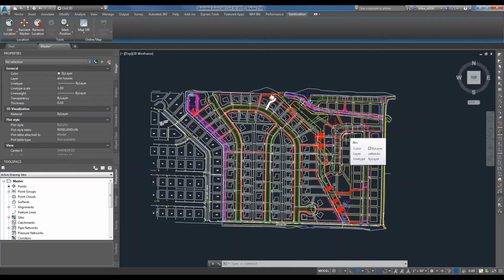However, in Civil 3D, we use COGO points, short for coordinate geometry points. They're a little bit different from those normal AutoCAD points. You could have plenty of properties associated with them. So you could have point numbers, point names, descriptions. So if you are surveying out in the field, you can bring in points with descriptions. You can tell them apart. So you can do top of curb, bottom curb, center line of the road, etc. So COGO points do allow you to have a little bit more customization. And they also let you have them outside the file, whereas in AutoCAD, they're inside your AutoCAD file.